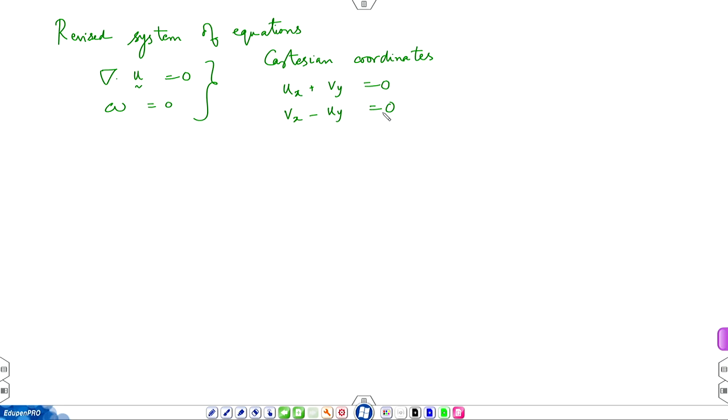So, this sure enough does not have pressure. What happened to pressure? We did del cross, so the pressure part of it went away, but you need pressure, right? Because if you talk about the force acting on the object, what are the shear stresses? Mu was 0 in this formulation. So, viscous forces are 0 on the object, forces will arise only because of pressure. So, you need pressure, pressure is very important. And there we work with the integrated form of the Euler equations.